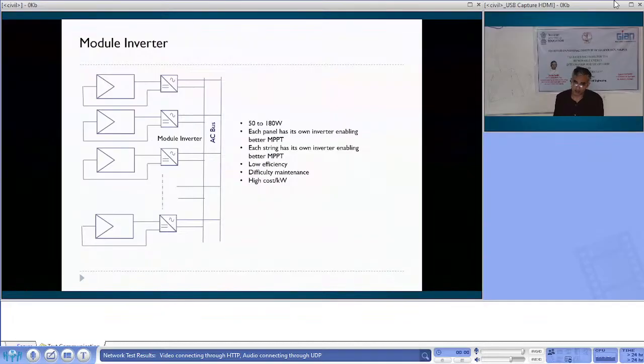The algorithm is maintained in that manner. To increase the voltage in a simple DC-DC converter, you increase the duty ratio. By a small amount, you increase the duty ratio, P, in small incremental steps. So your operating point increments in this fashion and tracks this point.